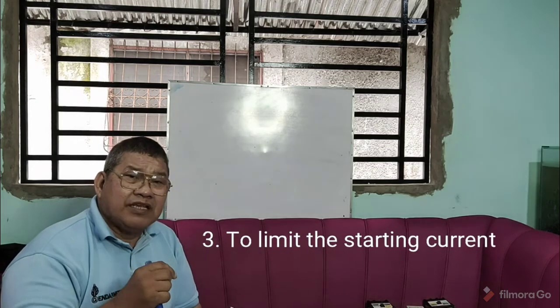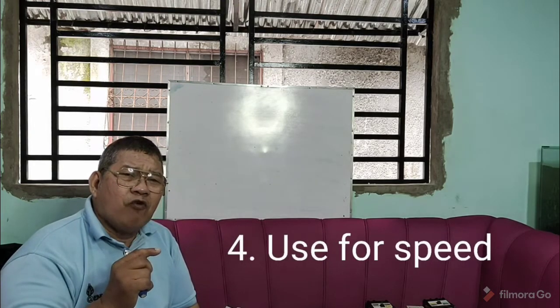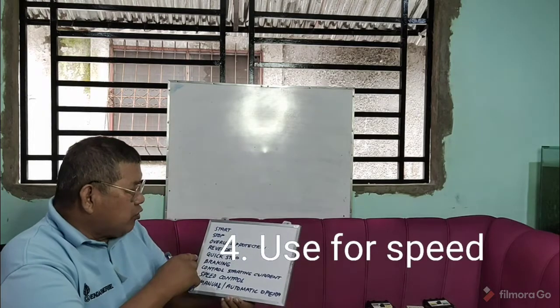Another one is to limit the starting current. Now remember, during starting, the motor will draw high amperes, 3 to 5 times of its full load. So if there is no, shall we say, a certain device that will limit the starting current, again, maybe electrically, mechanically, your motor will be in trouble. Then, aside from that, this is also used for speed control.